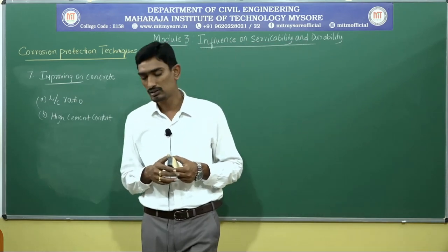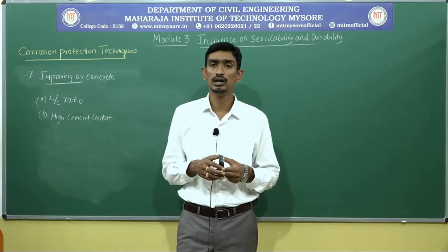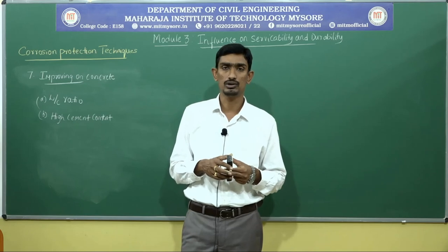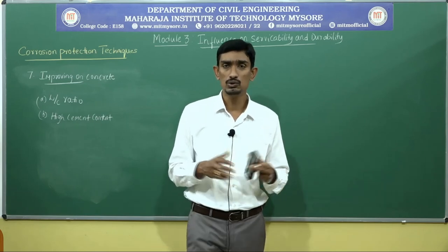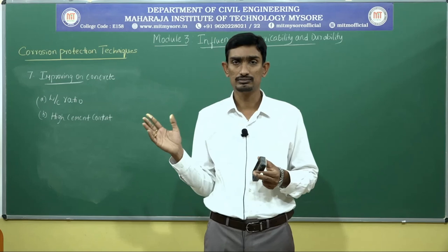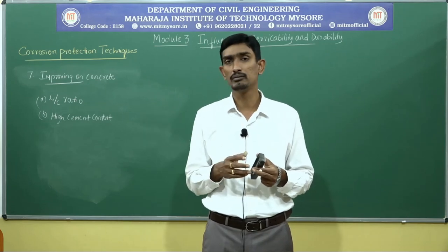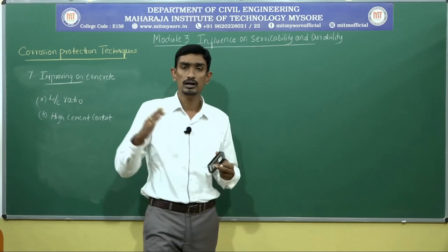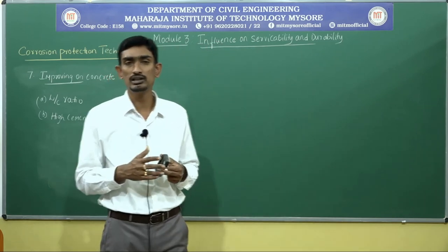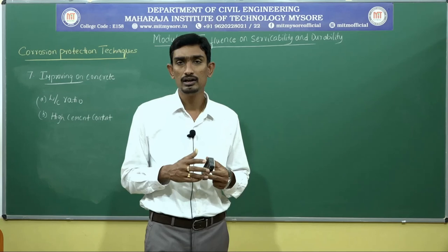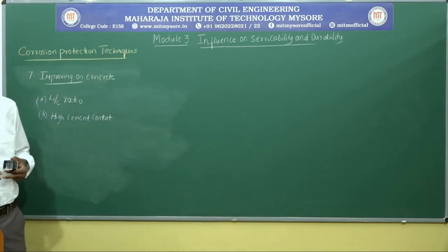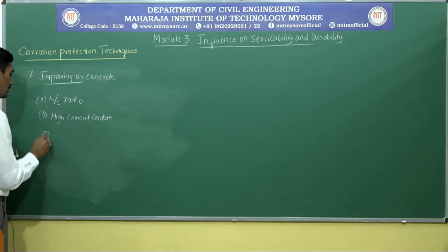But whatever cement content you are going to use should be within the permissible limit. So that is very important also. I cannot say use any amount of cement content, because I have stated high cement content does not mean I can use excessive cement. So by using the cement content within the permissible limit, I can go ahead with these things. Next is curing.